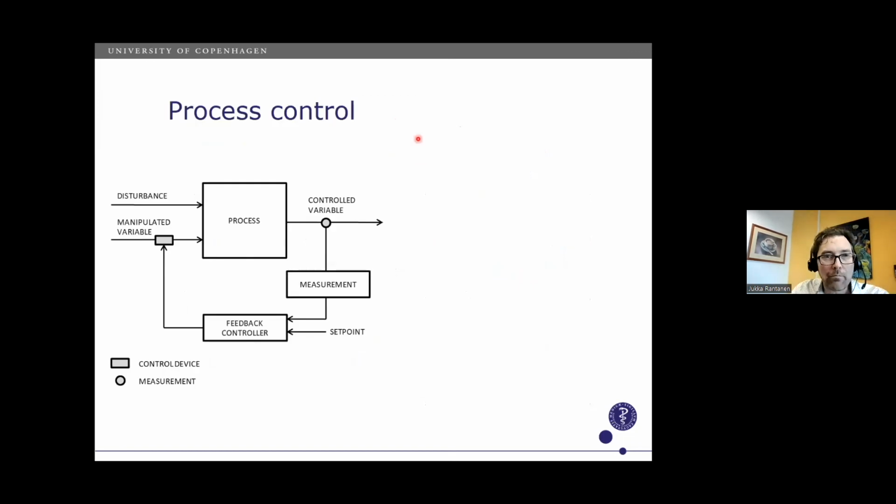And one important aspect of doing these process analytical activities is that you also implement process control aspects into the work. So here we have a schematic illustration of what process control means. Here we can imagine the controlled variable that can be measured, for example, the temperature of the air in the process, and you have a measurement of that, and a set point of that value. So you say that it needs to be 60 degrees, and then this measurement is saying that it's only 57.